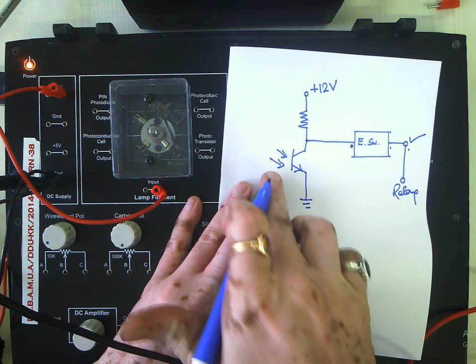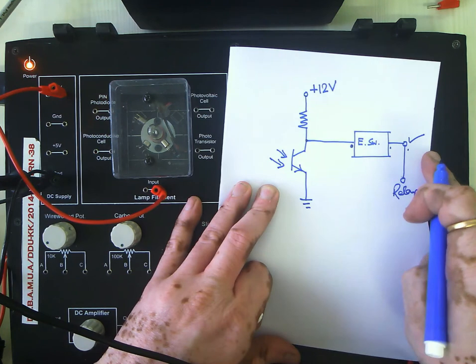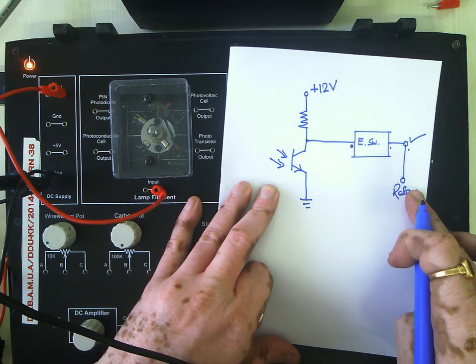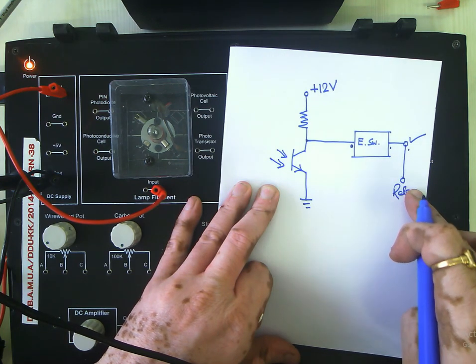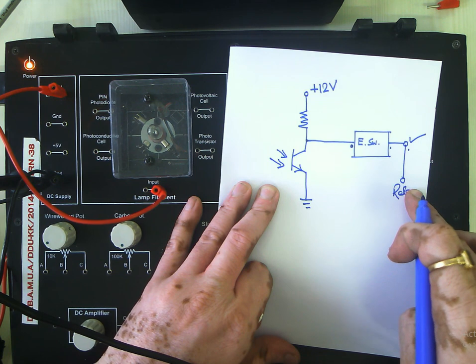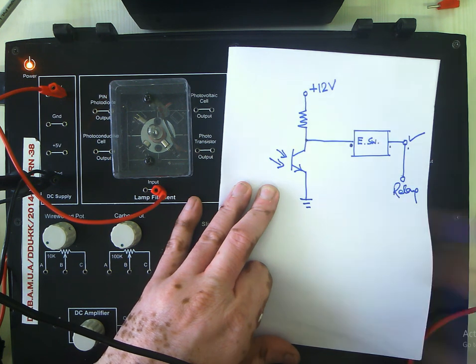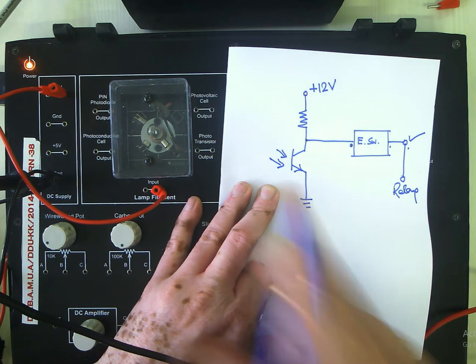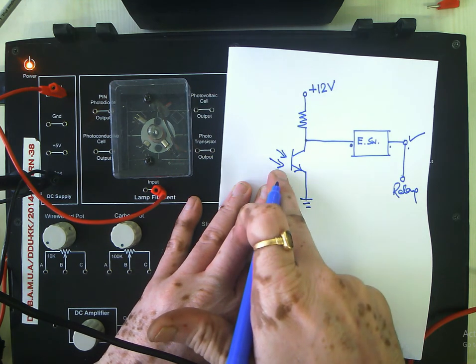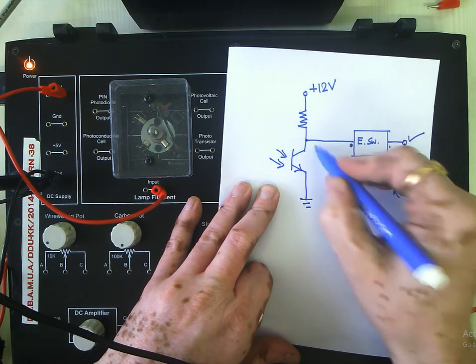So when there is dark, you will be having a high signal and your relay will be operated. Now you can simply use the NO terminal for your operation if you have connected a supply to the common terminal. Now when light will fall on the transistor, collector current will start flowing.